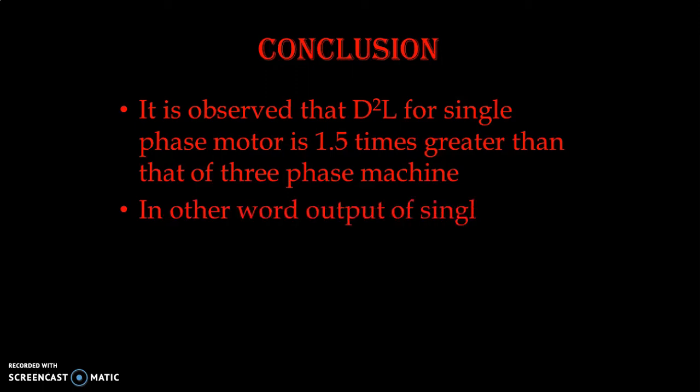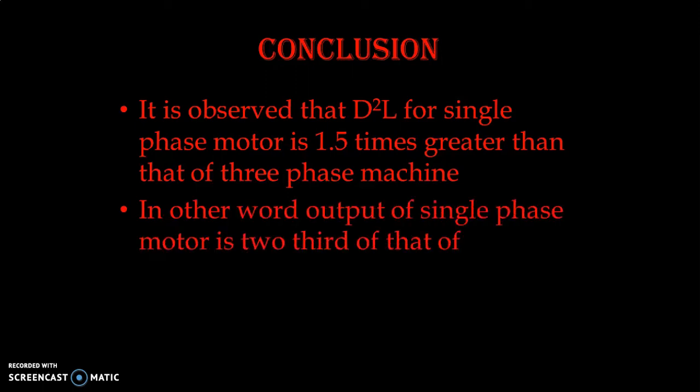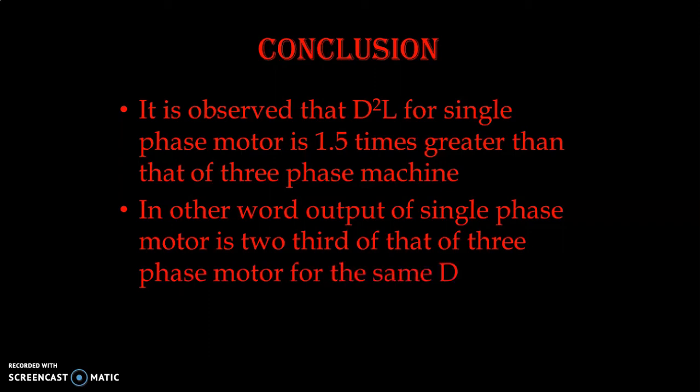In other words, the output of single phase motor is 2/3 of that of the three phase motor for the same D square L. This can be interpreted another way: if we go for similar size for single phase induction motor as well as three phase induction motor, then the output rating of single phase induction motor compared to three phase induction motor for the similar size is 2/3, right?